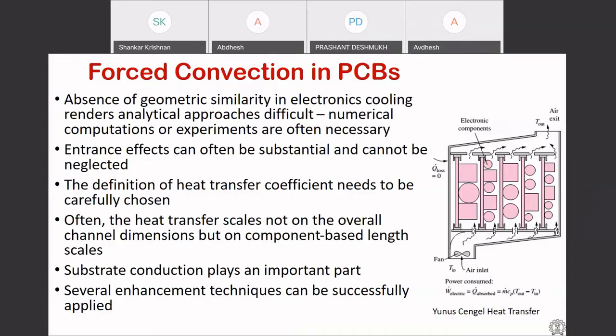So these days, most of the companies employ packages like IcePak to study or develop cooling solutions for these motherboards. Analytical solution is really not useful from the context of designing these boards. However, they are used as a way of designing heat sinks, at least as a starting point design, an initial guess for optimization of a heat sink.